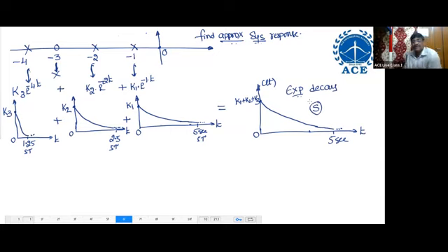The system is stable. That means if one pole or many poles are placed on the negative real axis, this is very important. By looking at a pole location, you should be able to identify the system response, system stability, and system time constant. So remember, left-hand side poles, blindly say exponential decay. It is the approximate response, not exact.